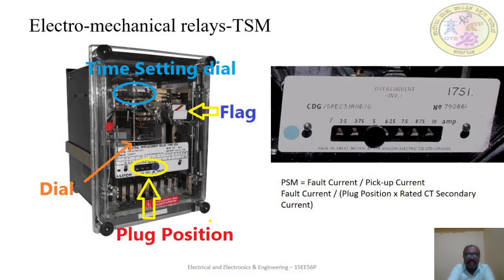In a power system consisting of generator, transformer, transmission and distribution circuits, when a failure occurs on any part of the system, it must be quickly detected and disconnected from the system. There are two principal reasons for it. First, if the fault is not cleared quickly, what will happen? It may cause unnecessary interruption of the service to the consumers.